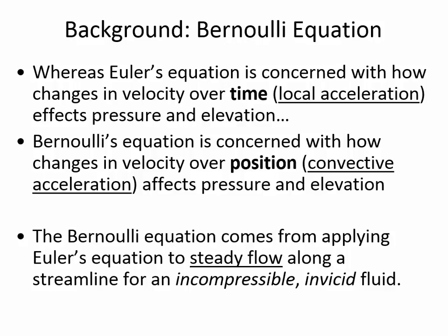And we can experience that as we walk through the air. There's a lot less resistance to our movement compared to when you're moving through a liquid like water. So it's kind of ironic that in one sense Bernoulli's equation is better for liquids because they're more incompressible. Then on the other hand, Bernoulli's equation is better with gases because gases are closer to the inviscid assumption.